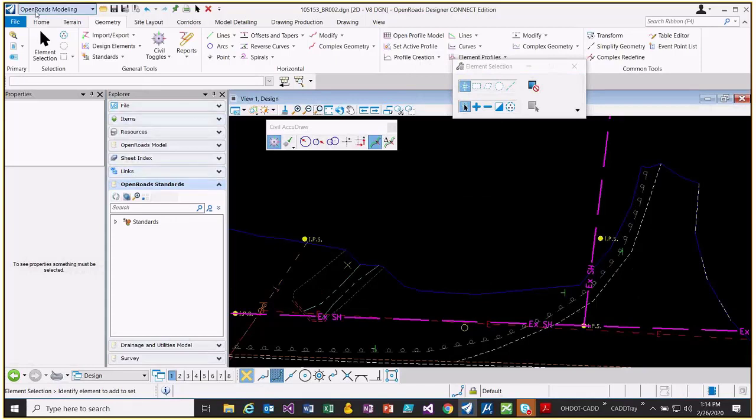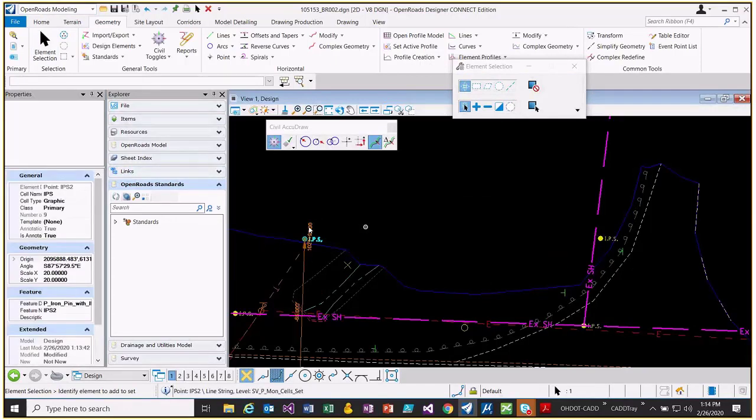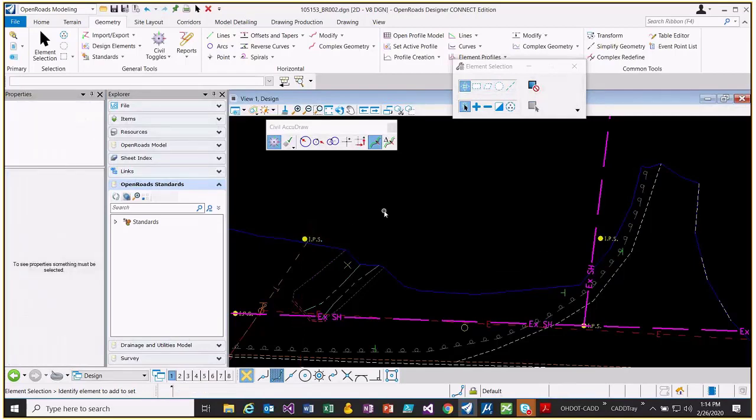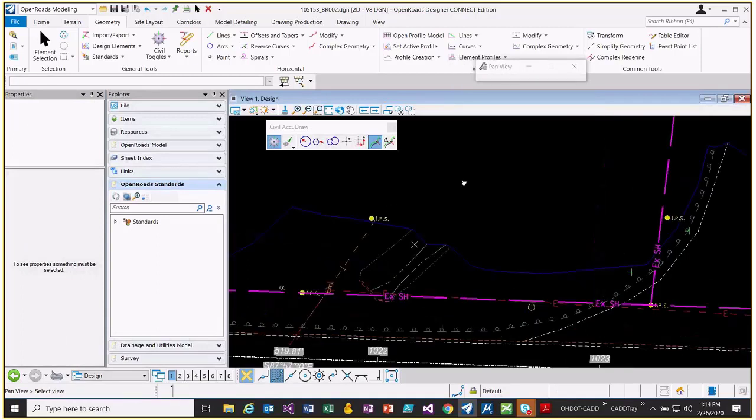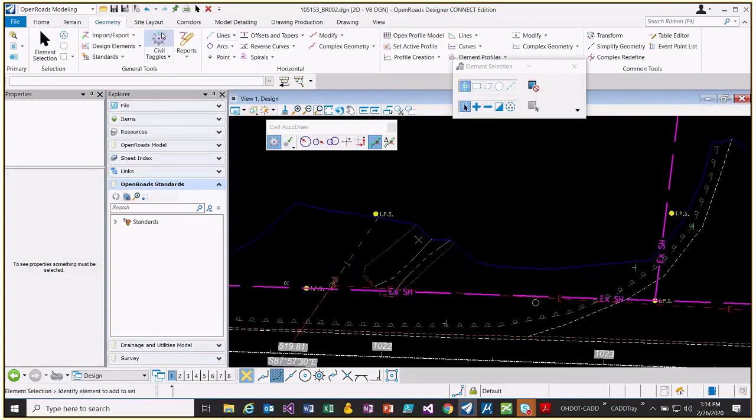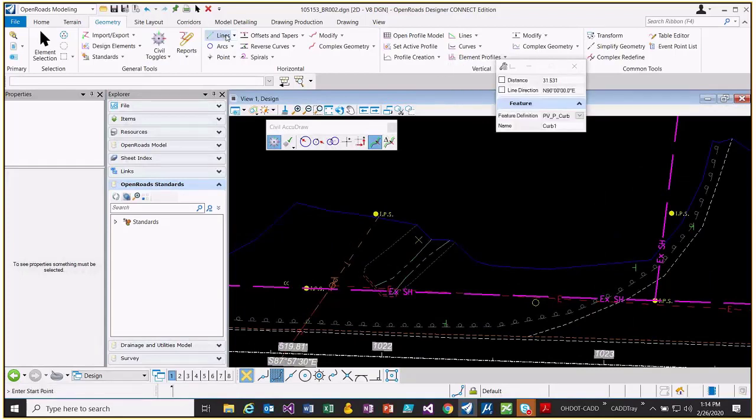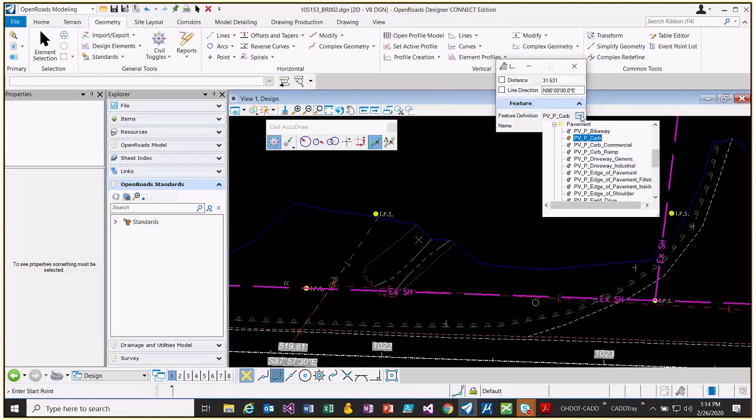So using Civil Accudraw, those are all ruled. If I select that point, I can see its station and its offset rule. So if I need to make changes to that, I can just change that rule. So I'm going to take this and make a closed area from this. I'm going to use in my geometry tools the line between points command. And for this on my feature, I'm going to use a parcel area feature. So that's a category of just some.